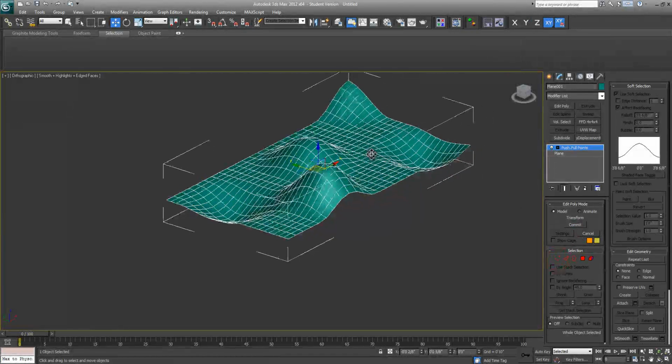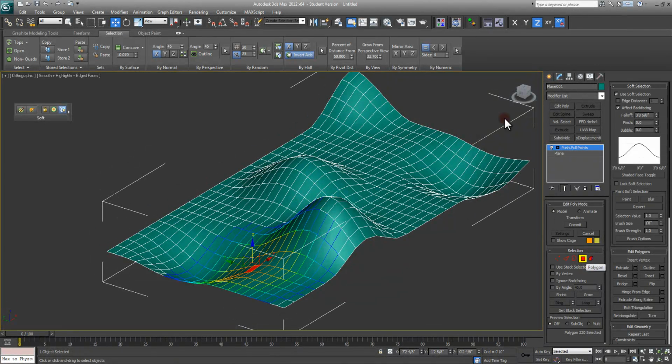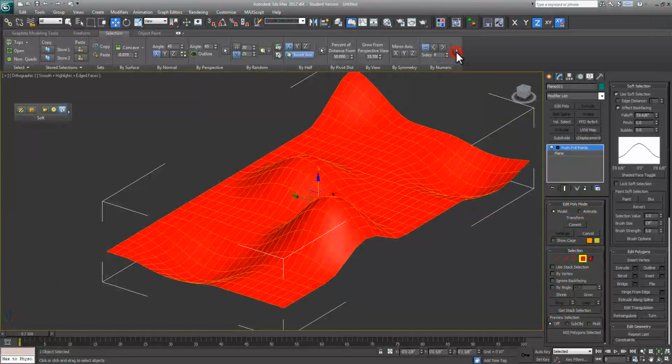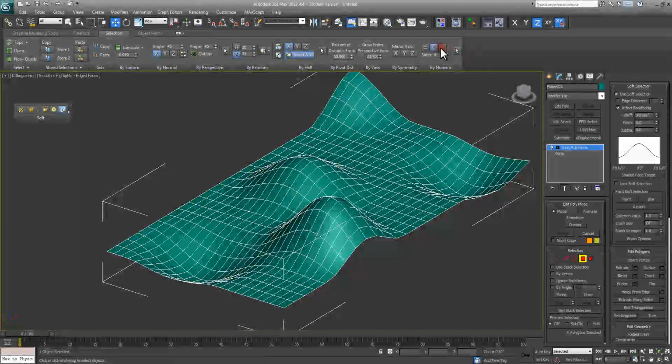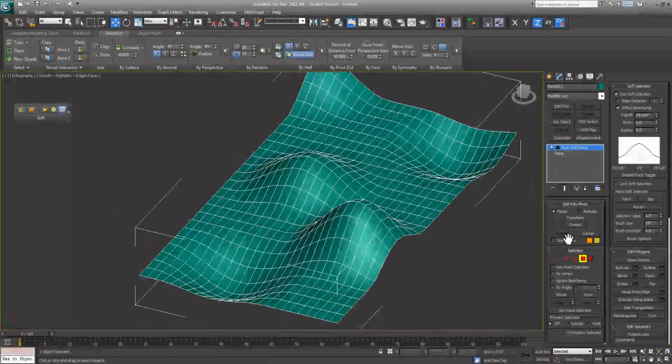The other interesting thing that you can do is, if I go back into my polygon sub-object over here, you can select by number of faces, and right now basically all faces have 4 sides to them. So if I hit everything equal to 4 and I hit select, it selects everything. If I do less than 4 and hit select, it selects nothing. Greater than 4 and select, it hits nothing. So say I want to get some different geometry within the shape here.